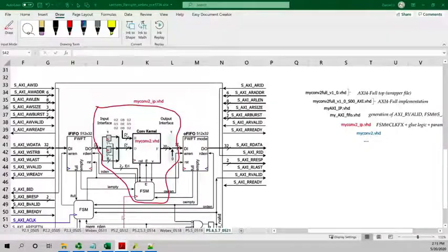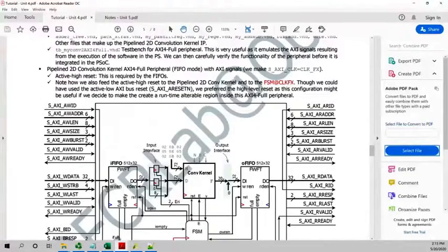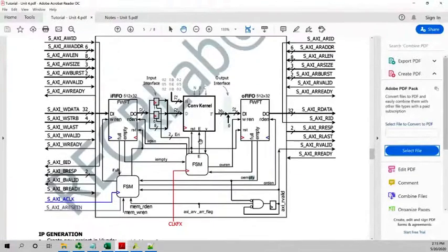The tutorial, I mean, there's nothing new. This block here has the input interface with 2 registers, such that, remember, we have 72 bits. We have to load 72 bits, right? Here we load 64, and then the remaining 8 are taken directly from the 5. And then we build the 72 bits right there to fit. The output is 20 bits, so we don't need to do anything except pad with zeros to get to 32 bits. It's not a big deal. So let's do that then.